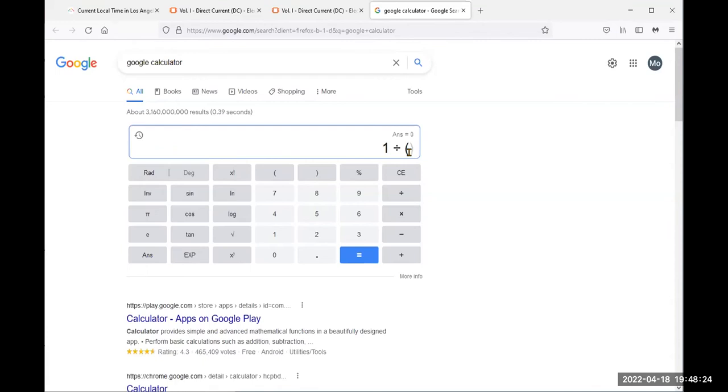When I taught the DC class, the next level class, I remember a few students had the issue most of the time, forgot to enter the parentheses, and then the answer at the end is wrong. Many times they made the same mistake. So 1 divided by, and the next thing is 1 over 100 plus 1 divided by 120 plus 1 divided by 240 plus 1 divided by 680.